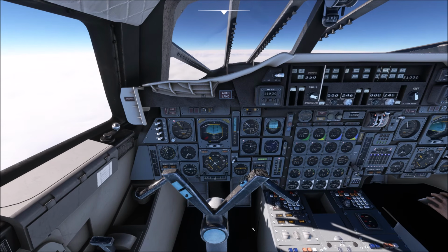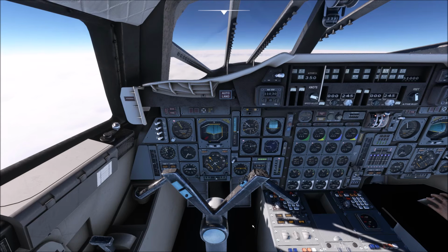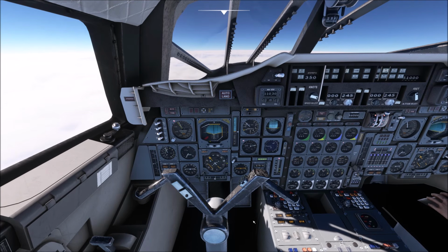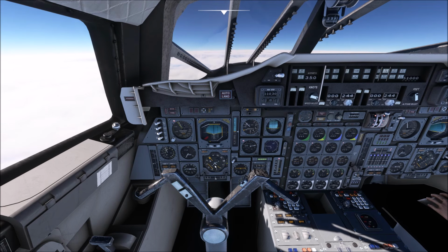And of course on the other side of the flight, it's just the descent down to wherever it is you're going to land, which you would commit to something like 200 nautical miles away from JFK. So, you would switch over then to radio nav, or you track the INS down until you can pick up the ILS for JFK and switch over at that point.